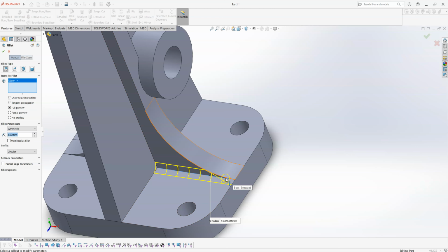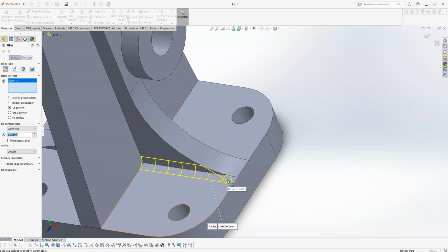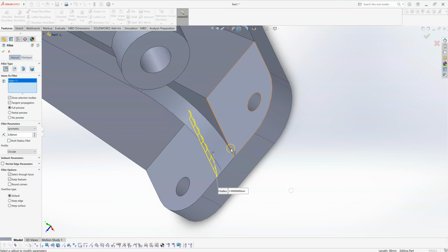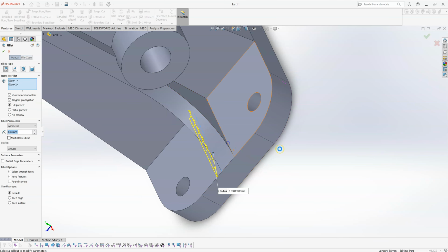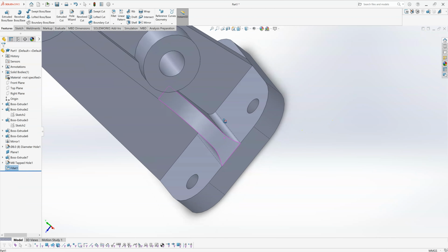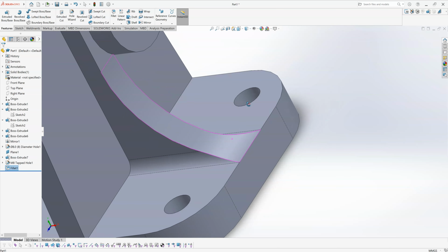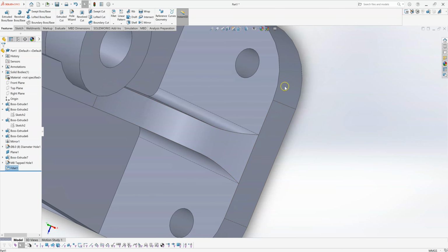if you try to fillet this internal corner here. So there are 2 different ways this can be filleted essentially. If you look down at the fillet options at the bottom here, there's a couple of different ways that can be filleted. So I'll just do it this way first, the default way. If I OK that, you see what's happened here is it keeps the outside edge of the fillet as a straight line, and it widens out the feature there to match. It's kind of fishtailed out.